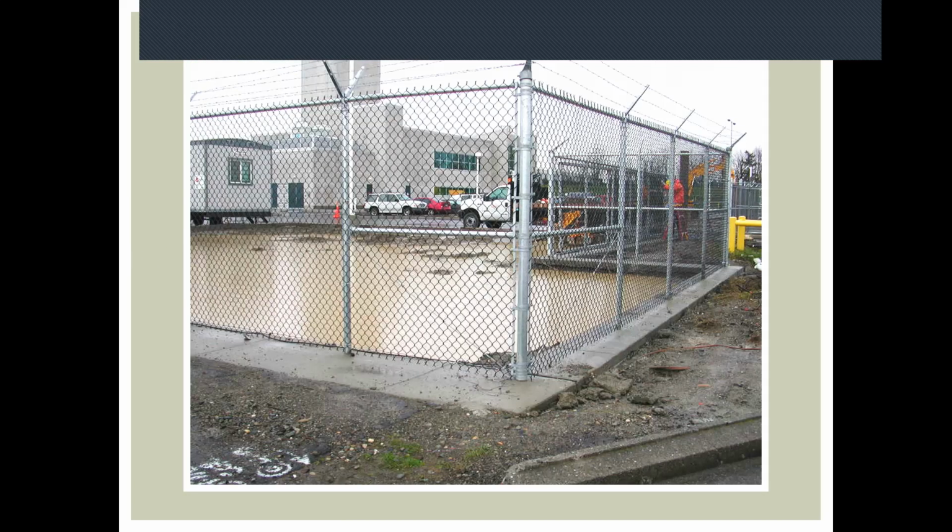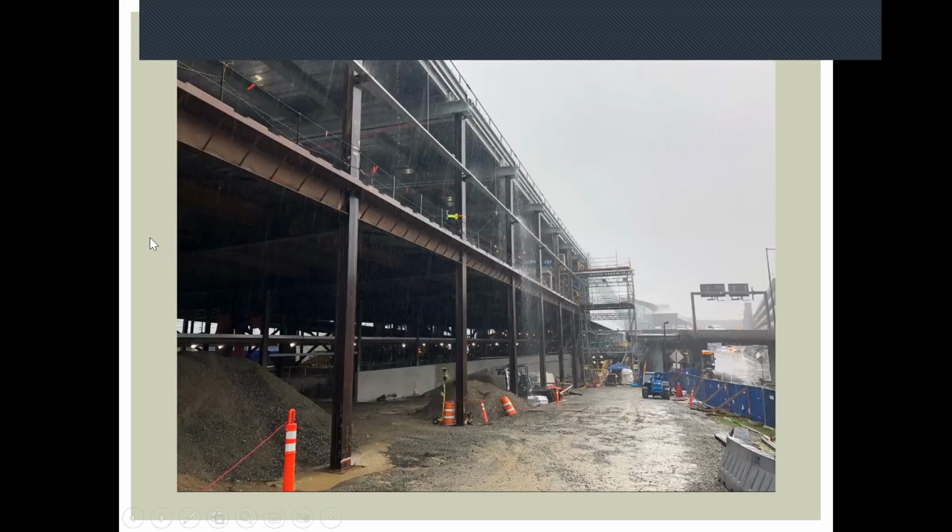Is this a good thing or a bad thing? I say it's a good thing. The water's not going anywhere. It's being contained on site. It's probably providing a little buffer area for the contractor. They can pump the water into a truck to haul it off. Potentially this is too dirty, but if the water wasn't quite this dirty, they might be able to pump it into sanitary. So yeah, always look for opportunities to do things like this and work with the contractor on that. Roof drainage.